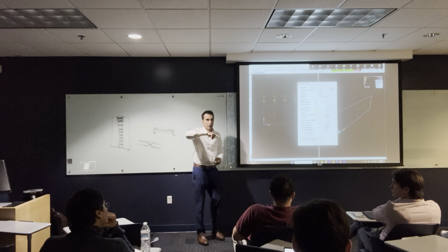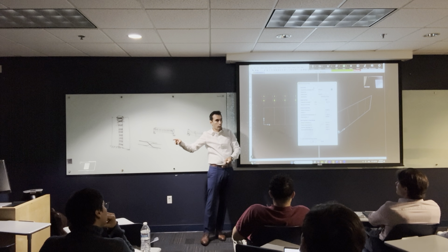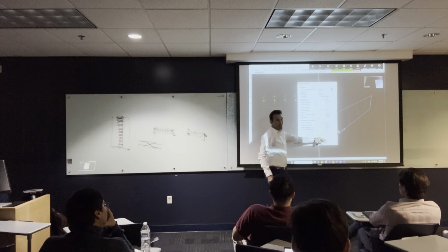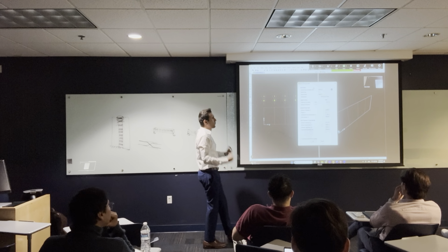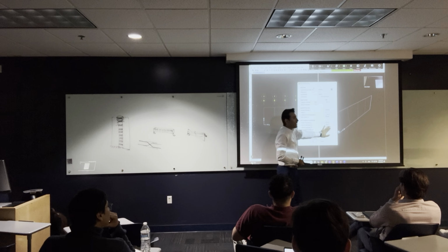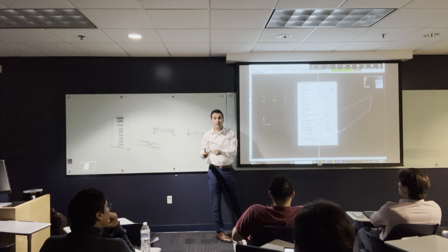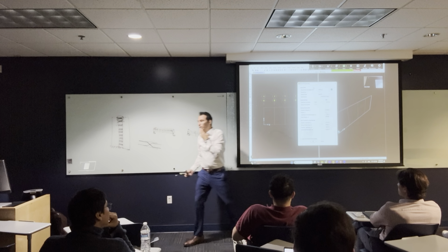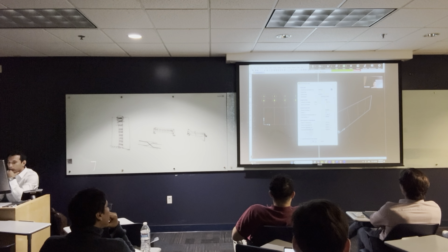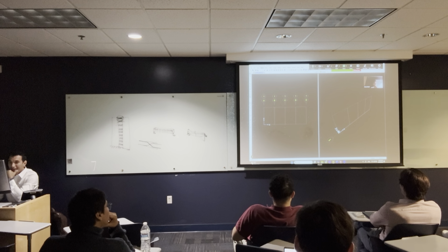If you remember the curve of the steel, it goes like this, and then it yields, and it goes to a maximum, and it goes to a breaking point. So here you put all the information about the curve for the steel, because that's what SAP2000 uses for design. For me, I'm not going to define these right now, because we are only interested in analysis. I'm not going to hit the design button over there. I'm only going to do analysis, because in this course I'm only interested in internal forces. So I'm going to keep the materials the way they are, and then I'm going to say okay. All right, so that's defining materials.